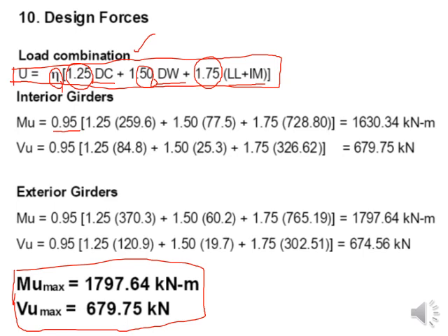Okay, so variant and invariant means static loads. So static loads and dynamic, in dynamic you may have the variant and you may have the moving vehicular loads. So all types of variant loadings that are enlisted in the specification can be incorporated by using this factor mu. Actually this is 0.95. Rest, the moving vehicular loads and the dead loads, we are considering in this bracket, but we are not considering the other types of variant loads. So to consider the effect of those, we use this mu factor, because a bridge is not a kind of structure that is ignored by these types of loadings.